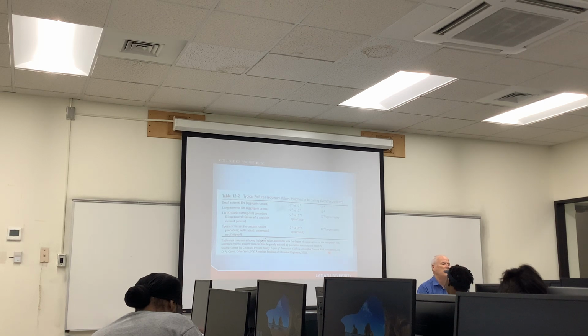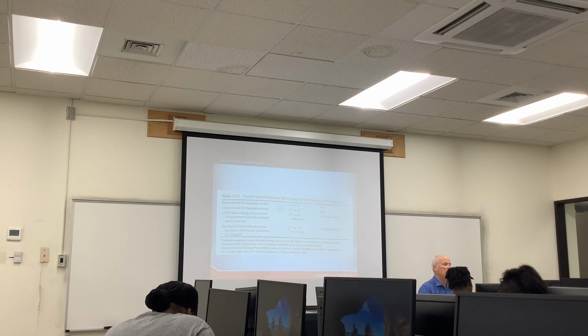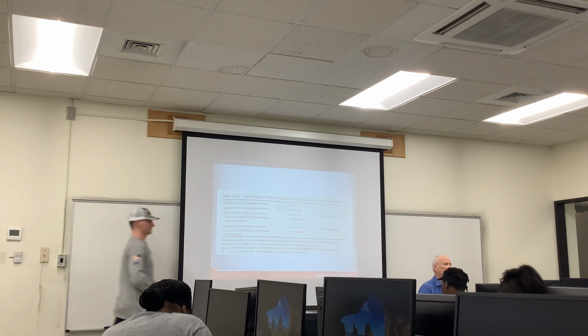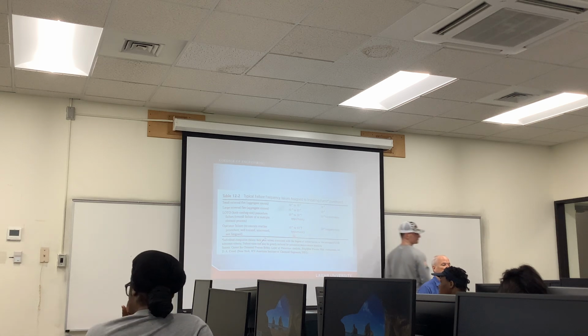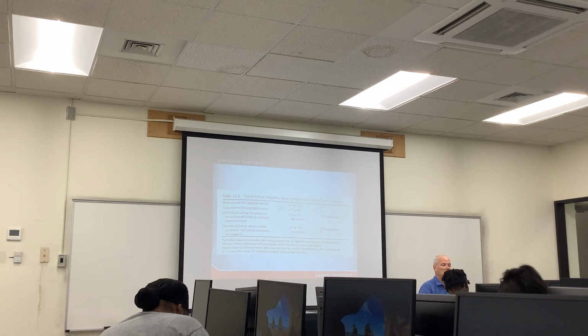All right, and interesting too, that operator failure has a big range, from 1% of the time failure to a lot lower per opportunity. So the 1% is typical, but if the operator's under stress, it could be 1 out of 10 times that they fail. So you have to consider that.